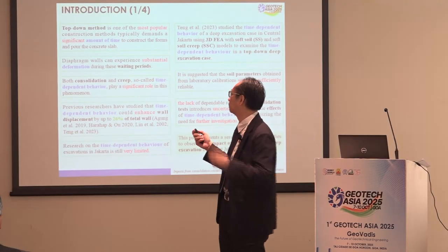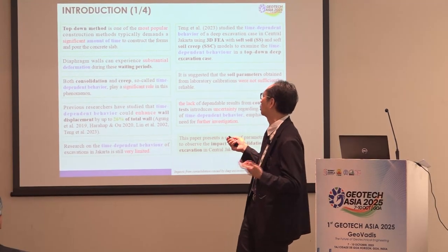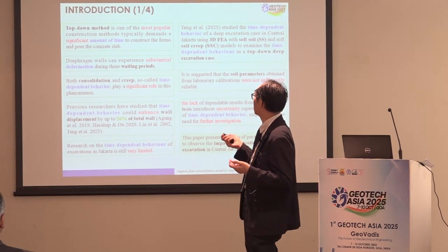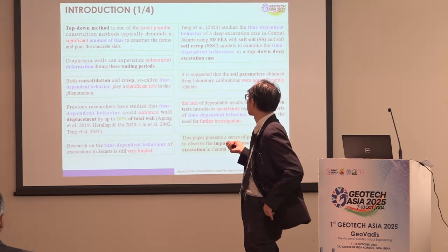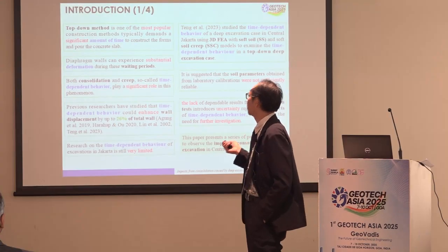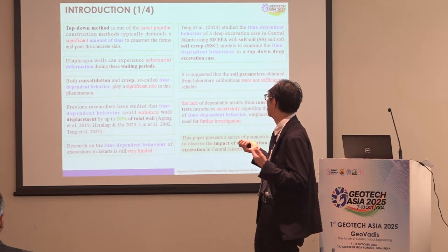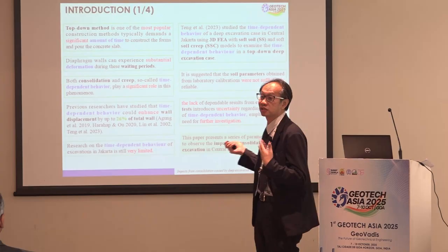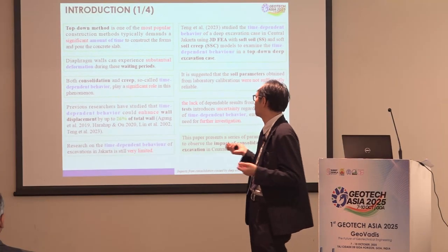So really, we may have more deformations of the D wall, and both consolidation and creep, so-called time-dependent behaviors, play a significant role in the phenomena. That's the reason why we want to talk about the time-dependent behavior.